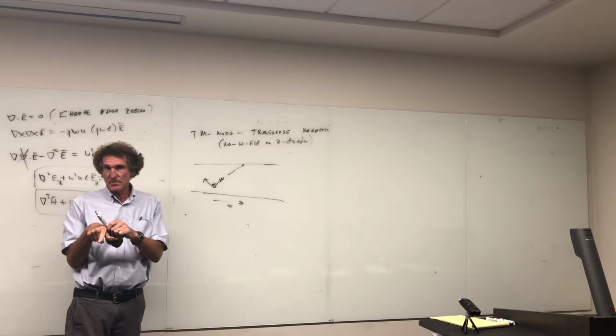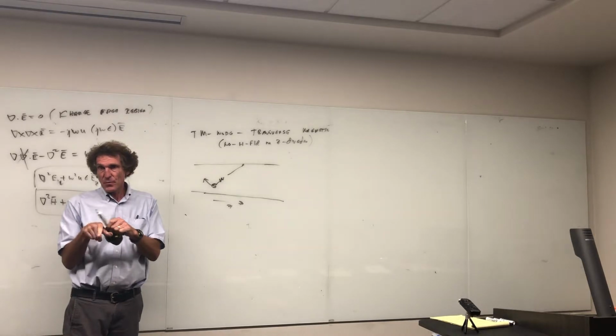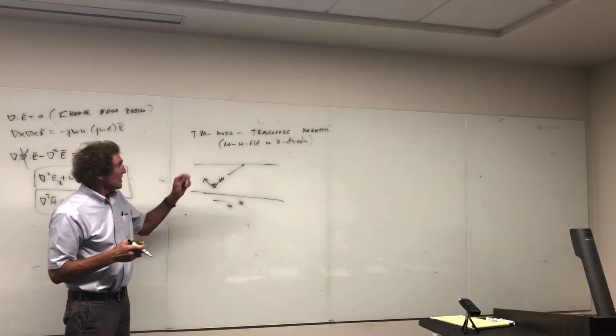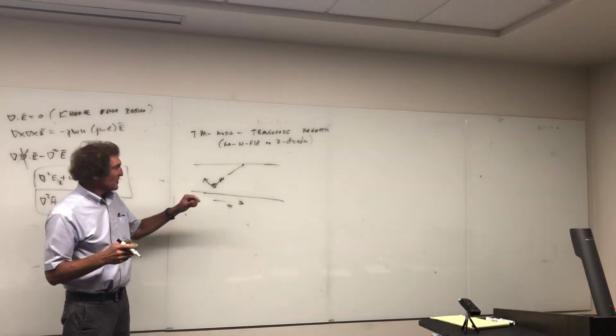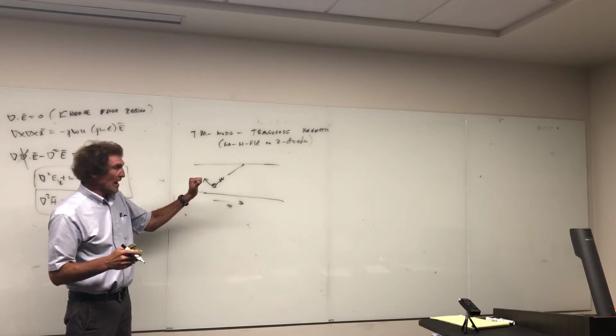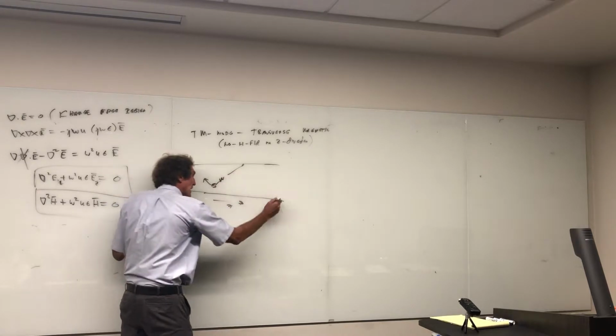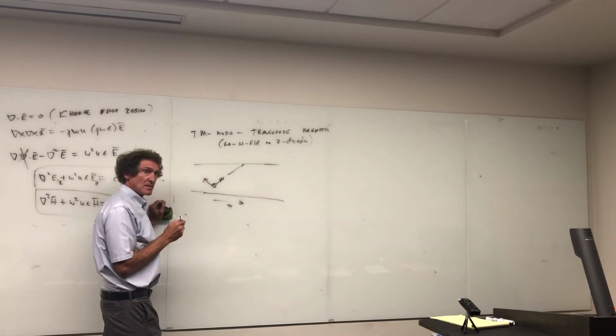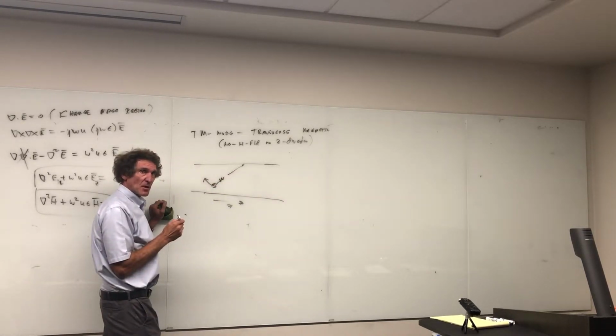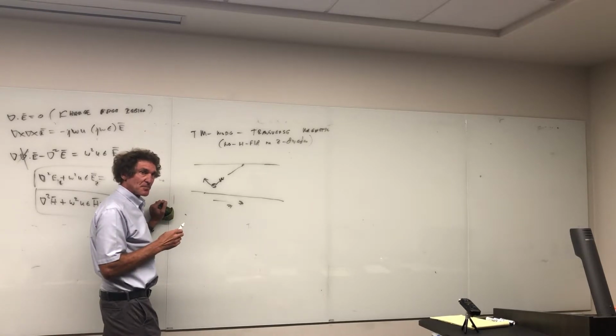If magnetic's out, E field has to be in the plane of the board. Do you follow me, class? So for TM, the magnetic field's out of the board, or out of the plane. This is the magnetic field, and it's going around. And that would be TM. There would be an E field in the direction of propagation. I'm sorry, I said that backwards.